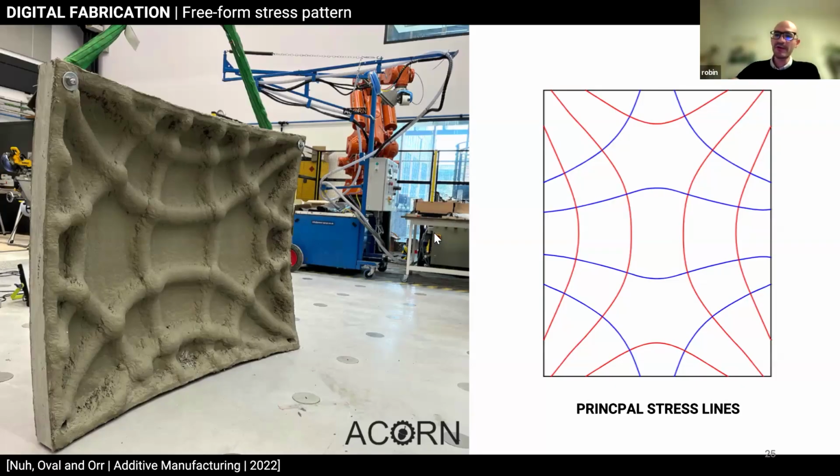So that was concrete with glass fiber in it. And with the robot, we could actually nicely spray those, following in that case optimal lines in red and blue. But that was key. So we have this complex topology, so it's not necessarily intuitive to know in which order to go through. Because when you spray concrete, you don't want to pause, because otherwise you make a mess. So it was an idea of path planning, traveling through these edges.